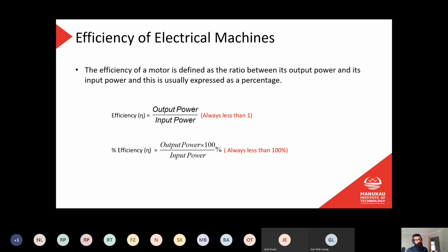We will, if you're just looking at the nameplate of an air conditioning unit or a heat pump. Sorry, when I talk about air conditioners and heat pumps, team, if you're not aware, that's exactly the same thing. It's just two words for the same thing. It will be technically more efficient. The amount of energy that I'm putting in will be less than the amount of heating that I get out. And that's why we use heat pumps, because efficiency-wise, they're way better than any other heating option.